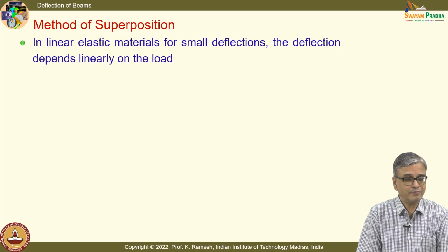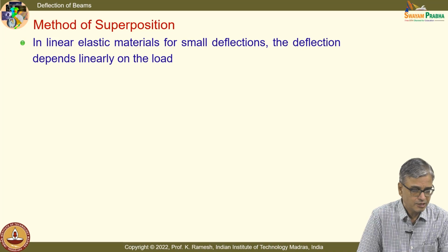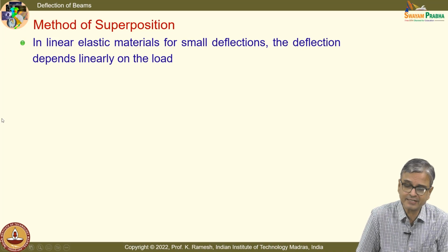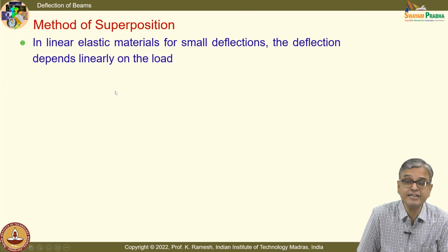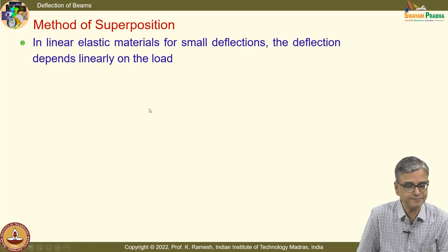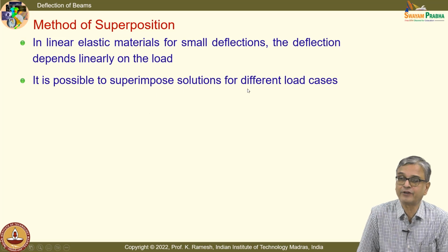So, we would focus more on the method of superposition. You have linear elastic materials, small deformation. The deflection depends linearly on the load, that is very important. It is possible to superimpose solutions for different load cases.